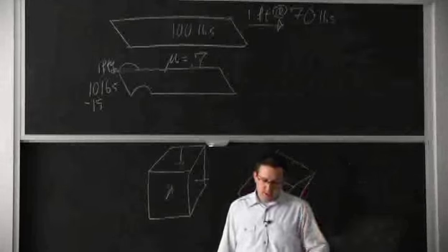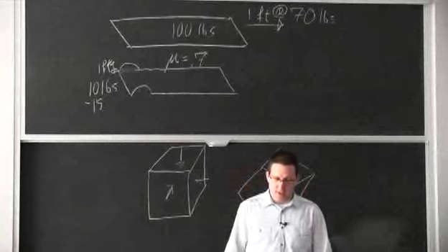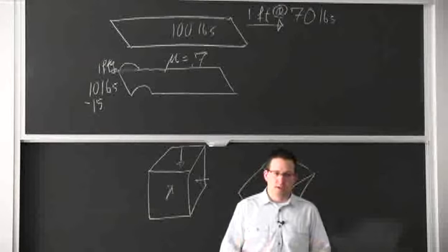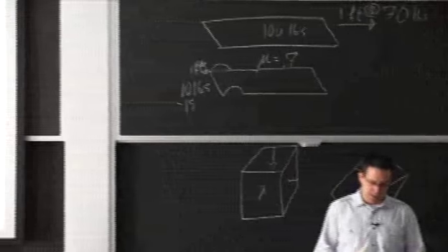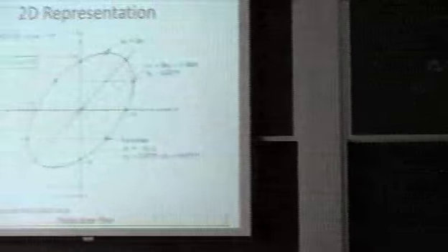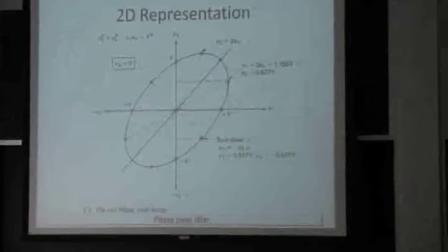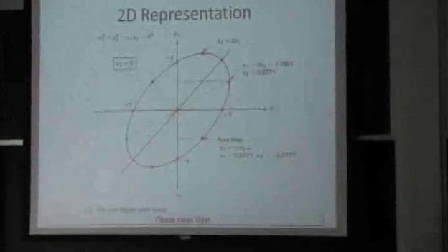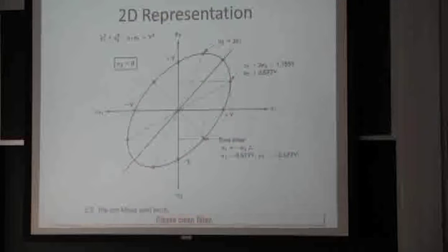That was probably the most theoretical aspect that we're going to cover today. Now we're really going to try to capture off of it for a very specific application. So a 2D representation here means we're taking one of those components, sigma 2, and we say it's 0. So now we're working in a plane, and our cylinder has become this yield shape, the yield locus.